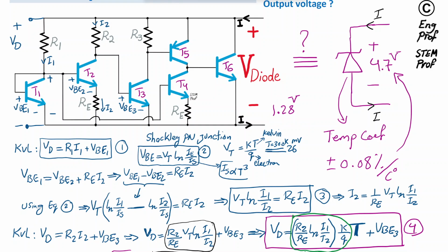Now, as I said, the main current-bearing transistor is T6. So we can now design components as a part of making sure that just a minimal amount of bias current is passing through this element. So for example, just as an example, you can do it with other values you would like, I can set I1 equal to, say, 0.5 milliamp or 1 milliamp, doesn't matter.